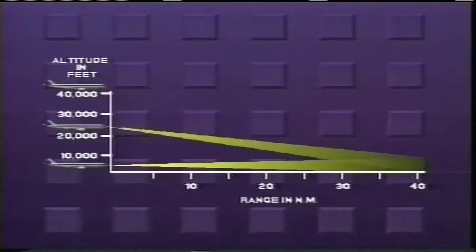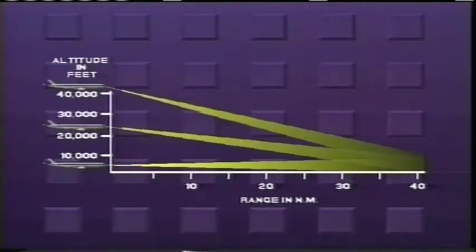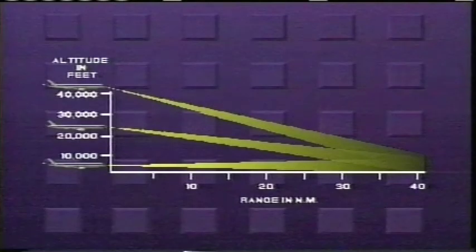If you change altitude, consider the geometry of the scenario. If you descend, you need more up tilt to display the correct radar picture. And if you ascend, you need more down tilt. You should adjust your antenna tilt each time you significantly change your flight altitude. Coupled with the requirement for good tilt management skills is a requirement for good range management skills. Range management means to choose the radar display range that is proper for your flight altitude.